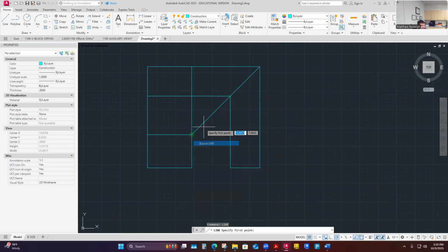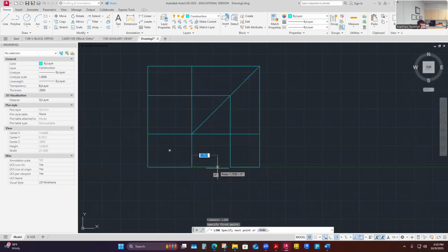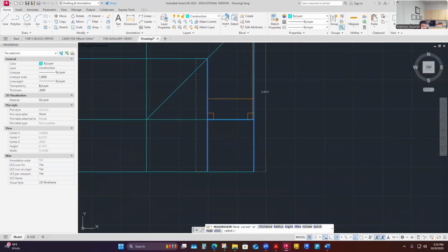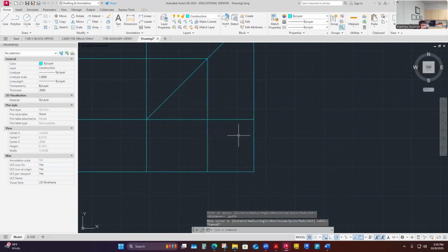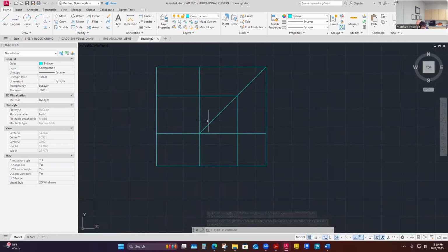Cap that off there. And I'll finish capping these off here. This is my right side view. This is a good way to check that your views are in alignment, that this thing should be 2 by 2 and a quarter. So I might just do a quick measurement here. Make sure I'm hitting my 2 by 2 and a quarter. I like it. I don't feel like I'm getting any distortion across my miter line here or from horizontal. So that's going to be my boundaries for my three views.